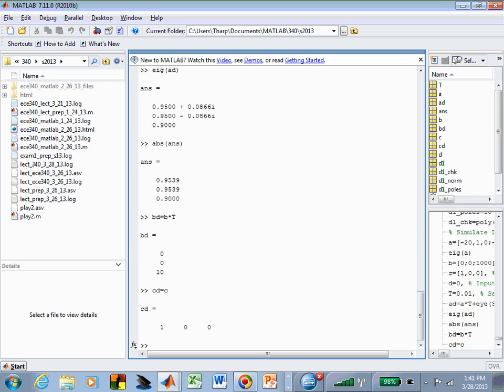What's the transient response going to be for this system, and how would I think about that? How long should I run this simulation if I was just interested in following the transient? I'm looking at the eigenvalue question. What do the poles tell us? Where are they? We're looking at the real part of those poles, aren't we? And we're looking at the slowest one.